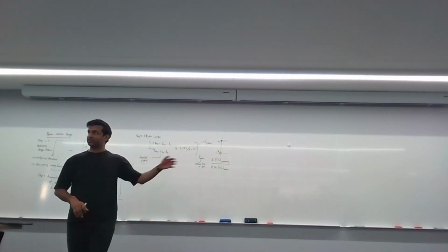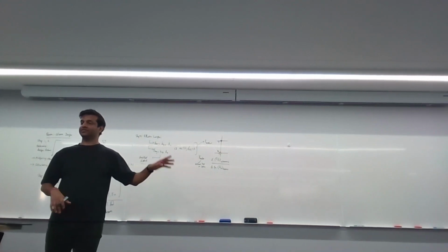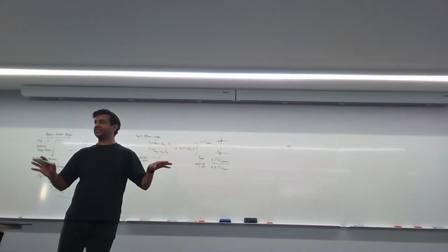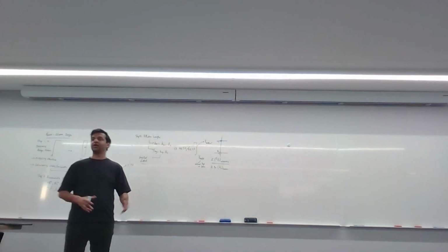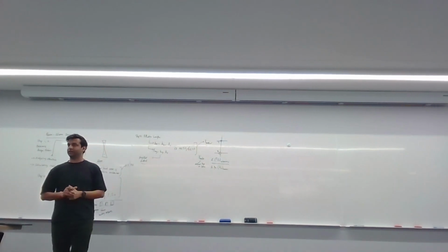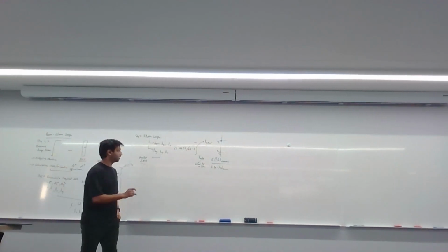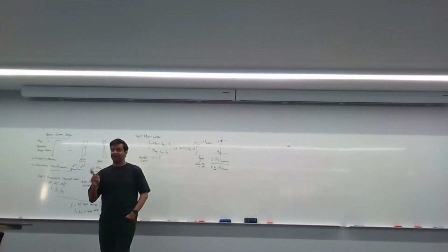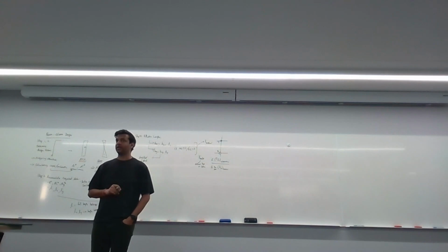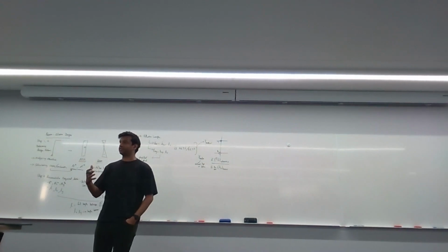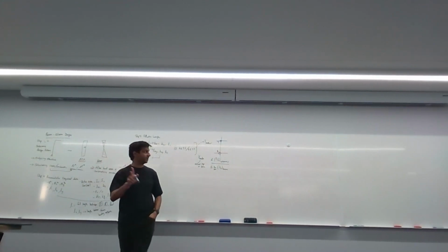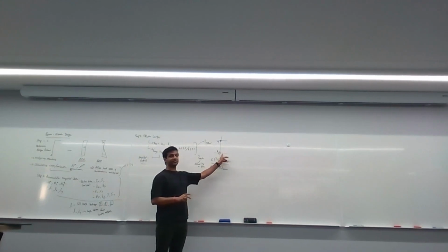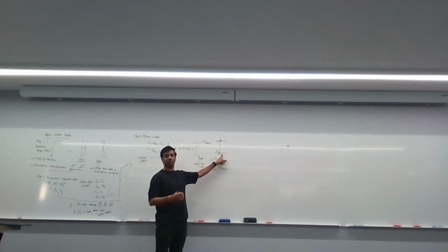Again, I'm not going to spend too much time on this because I believe almost an entire week was devoted to just the gamma method. This is just a recap. An important thing to note is beta E. Be very careful to choose the correct beta E when you're doing this question. So what is beta E based on? It's based on two things. Beta E is based on the connection of the beams on the close side to the columns.